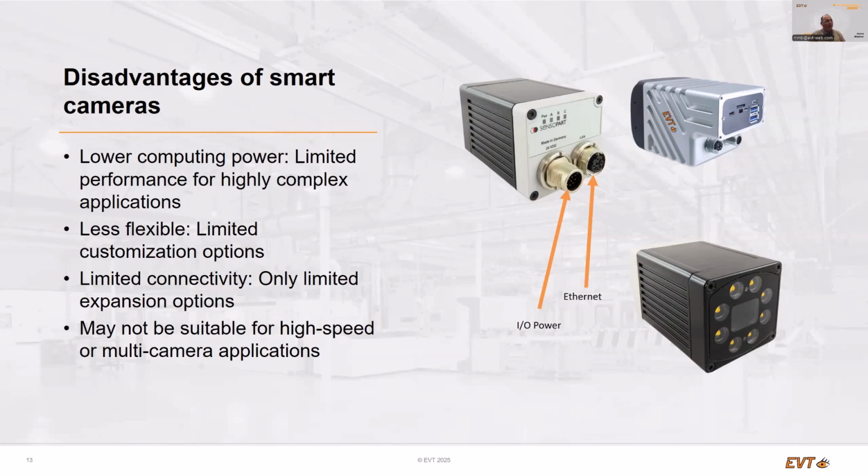Either you have to add more I/O lines over a special component like an I/O interface board, which you can connect over Ethernet, for example, or you need a PLC, and you connect over Profinet or Modbus with the PLC to add your I/O capabilities, as long as the machine doesn't support the direct communication.